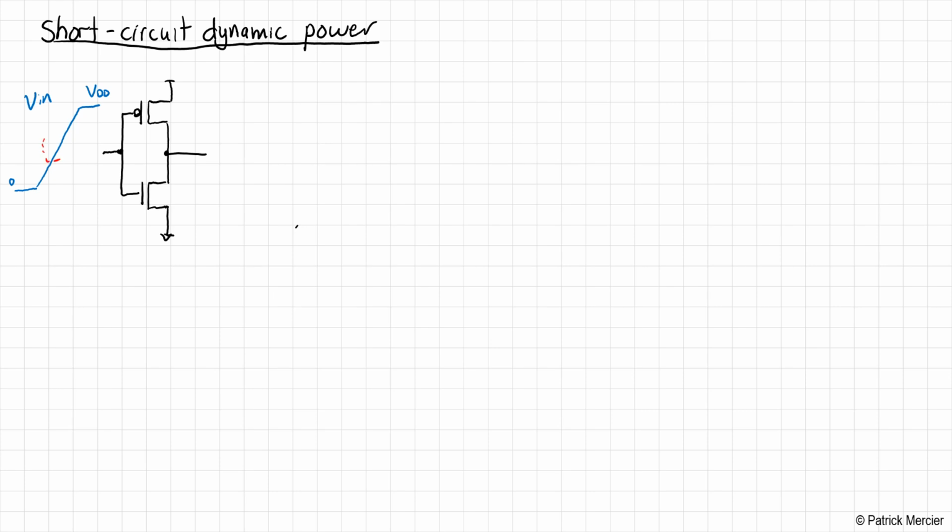So there's a region in the middle here, depending on what VDD is, but for most standard CMOS supply voltages, there's a region where both devices are on, both NMOS and PMOS are on and saturated. So when the input is around mid-rail, we have both of them on and both of them are saturated. Now this does depend on VDD. If VDD is very low, perhaps they never actually turn on, everything's operating in sub-threshold, but I think you get the idea.